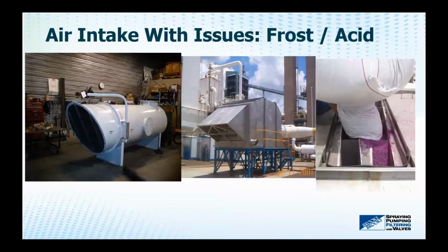But we're not always lucky to have nice clean air, so I titled this one Air Intake with Issues. Some of the issues that we are faced with, specifically here in Canada, is that during the winter time or just prior to winter, when the temperatures get cold, there's the potential of frost buildup on the air intake. If you have a certain velocity, temperature, and moisture content, frost will build up at the air intake.